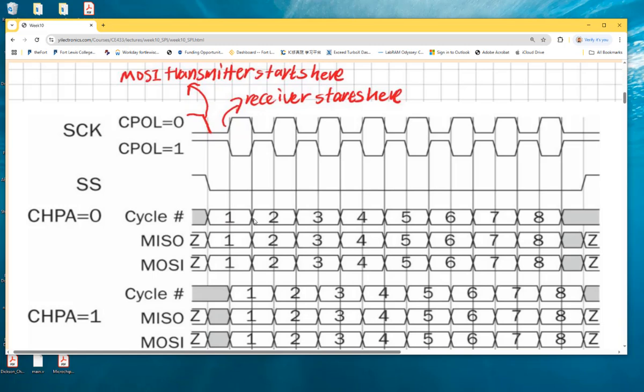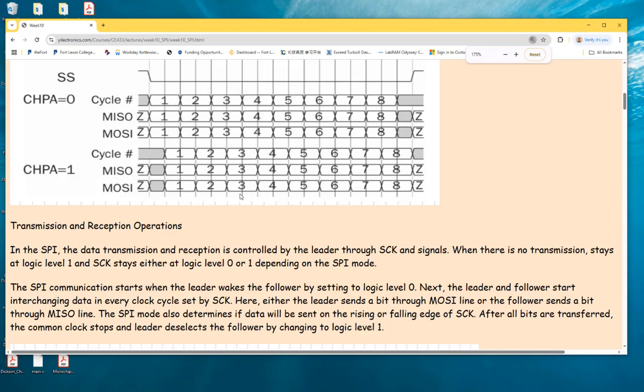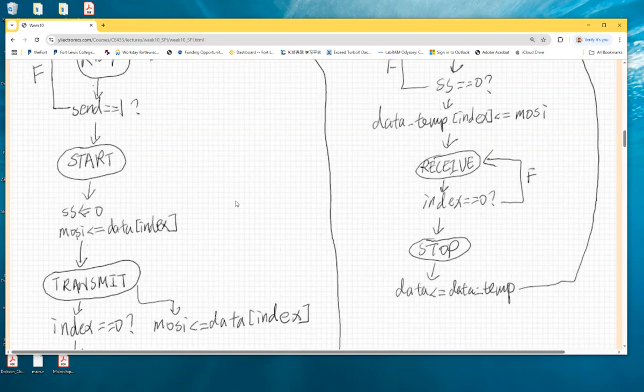So by that time, should that rising edge be in the middle of the data or at the edge of the data? In the middle. Why? Because that's the D flip-flop, right? It's an edge-triggered D flip-flop, so the data should be right in the middle, the most reliable data source. That's the way you find out which mode it is and how that mode is operating. It's pretty simple actually. We look at which mode you are selecting, and then you program your Verilog accordingly. Now let's take a look at the Verilog.